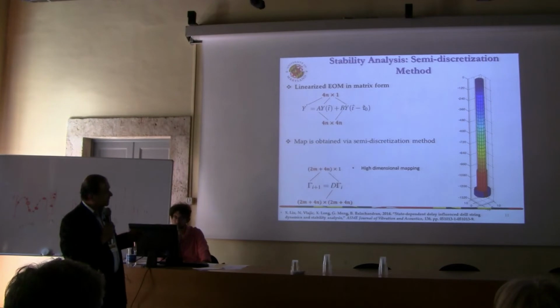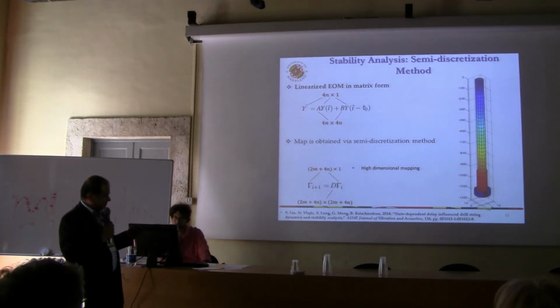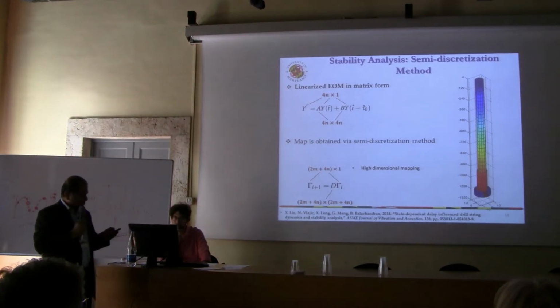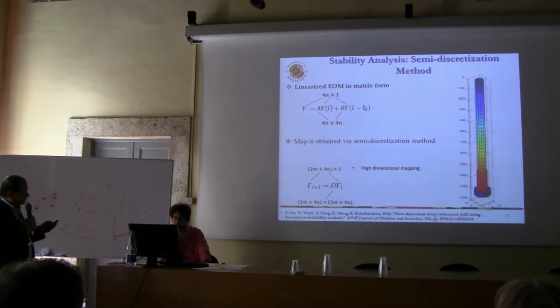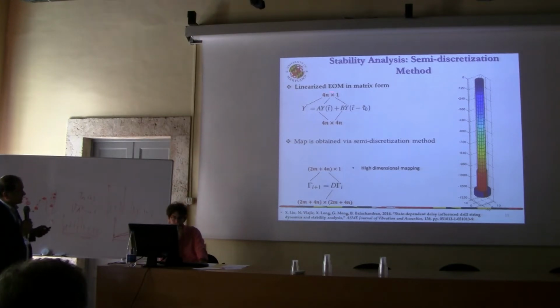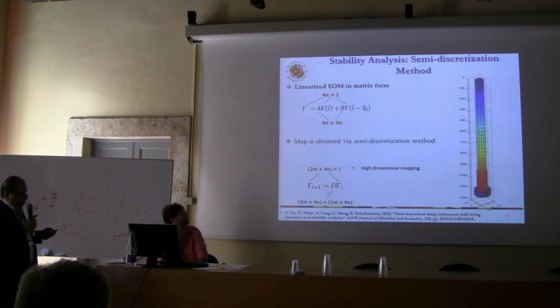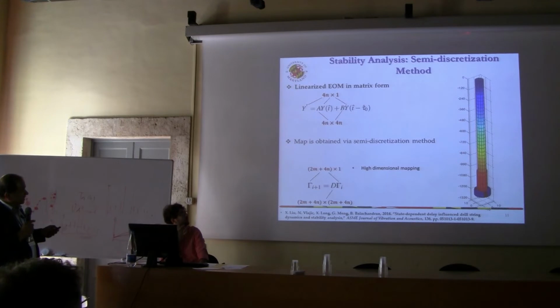Once we do that, then we can use the semi-discretization method that Insperger and Stepan have worked with. So before we get there, I take the nonlinear system and linearize it around a certain operational range, and then I take my delay, in this case divide it up into 40 segments, and that M in this case stands for the number of segments I have for the time period due to delay, and there's a number of states, so just 32 out here.